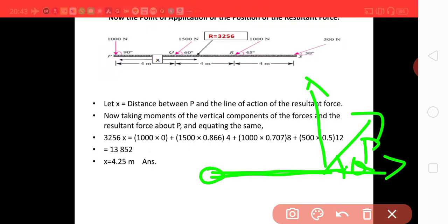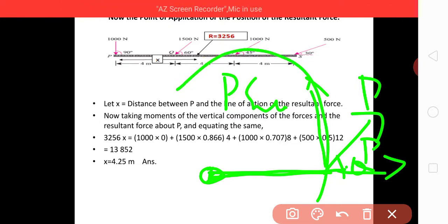This is a force P acting, then this is a pivot point above. This component, P cos theta, is giving it a pull at the hinge, but this P sin theta is giving it a moment, that is counterclockwise rotation.